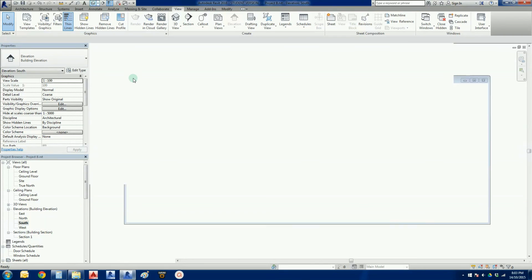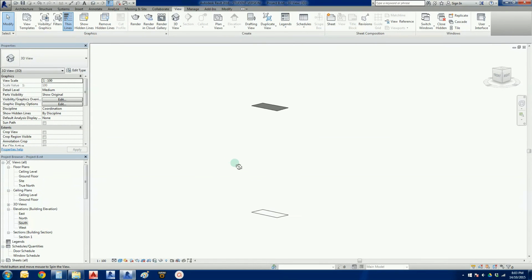Okay, but that's the bones of it. So this is our CAD file, and that's sitting at ground level, so that's sitting at 0.0, and now this is sitting at 100.1. Now, before I go, this is a common thing with what surveyors do in Australia. They use this 100 meters as an arbitrary datum or a benchmark. Generally, if you're doing 2D stuff, it's not a problem. With Revit, it can be a little bit of a nuisance.